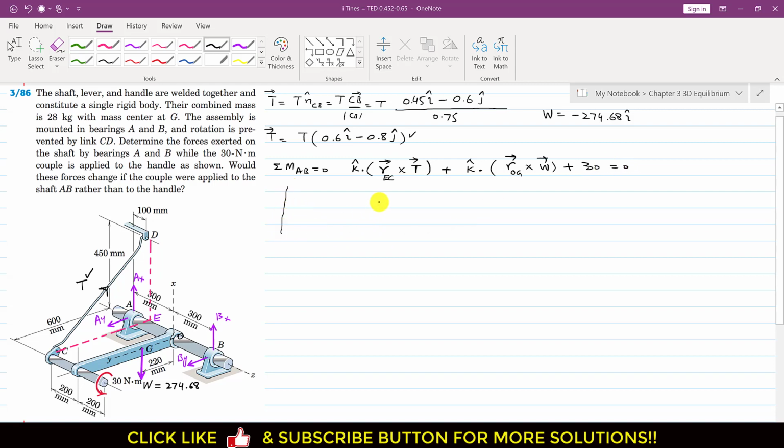So now we will apply the vector triple product, right? So this is k, so we will write the i and j components of this vector as 0, right? So we will write 0, 0, and this is 1, and REC. So the REC vector is, to reach that point C from E, we need to travel 0.6 meters along the positive y direction, right? So I will write 0.6, and the i component of this REC vector is 0, and the k component of this REC moment arm is 0, right?